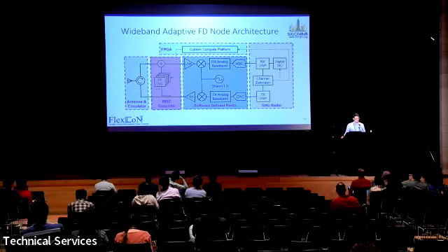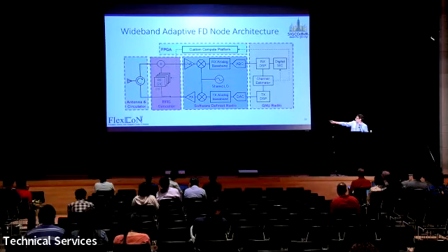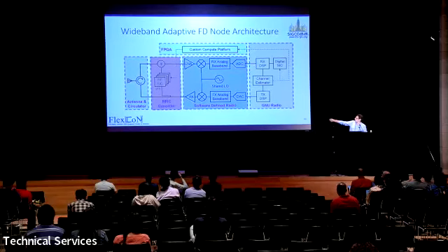So here's what we propose. Here's the node architecture that we presented at the demo at this conference. It consists of 5 primary components: the antenna interface, which provides that isolation, the RFIC, which I just showed you, the software-defined radio and associated new radio flow graph, and an intelligent FPGA platform, which performs the computations that you need.